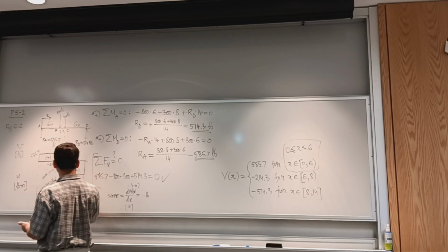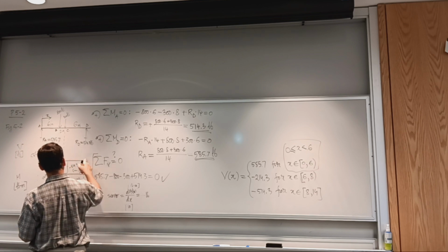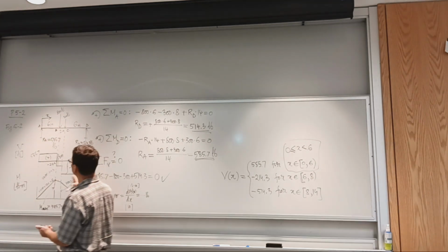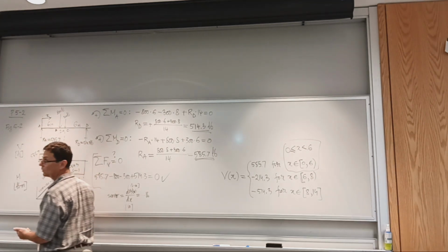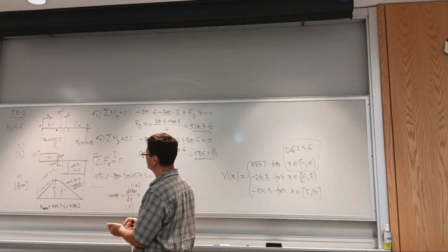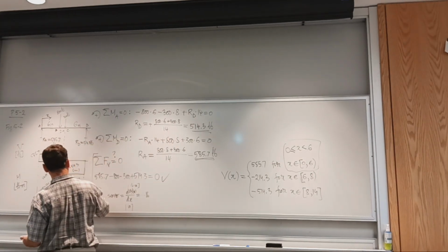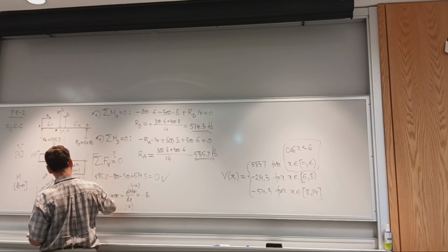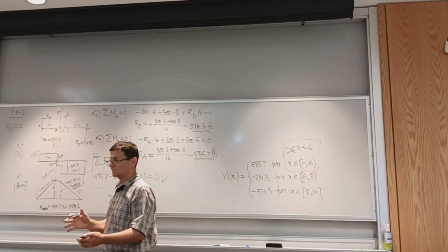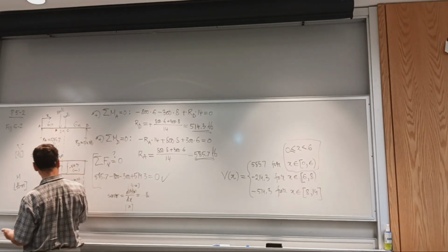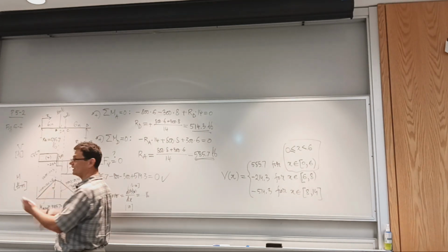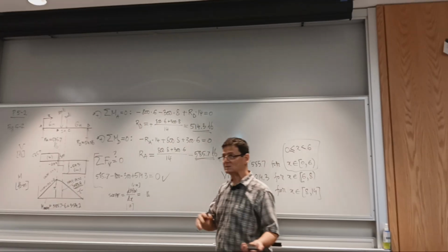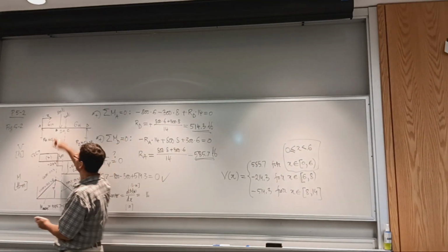I could get this same value if I take this area and change the sign. So now I go right to left. Sometimes it's more convenient. Instead of going 1, 2, I go with just 1. So it's also equal to negative. I change the sign because I now go from right to left. The book doesn't do this, but sometimes it's helpful because you don't rely on a wrong calculation. Or you can go both ways, and if you get different values, it means you missed something. Maybe you missed a concentrated moment somewhere, if it's present.